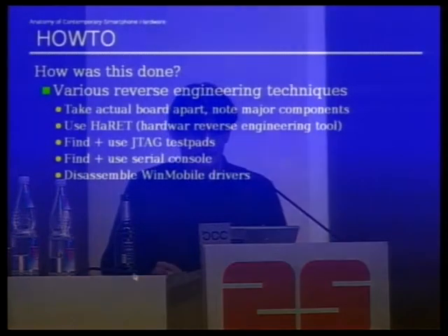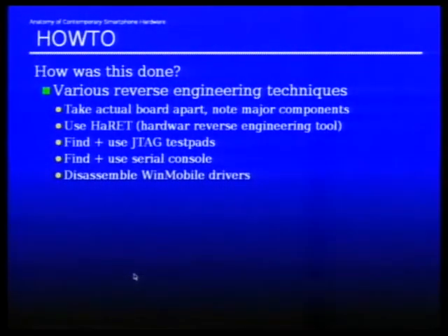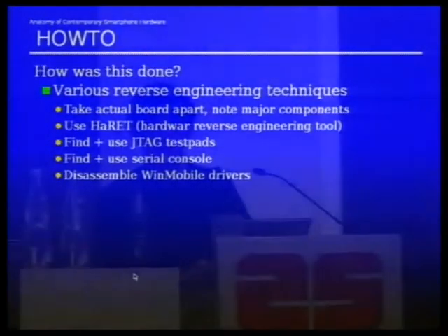So I started this project, the status of the project you can check somewhere else. So the question is, how does one go about understanding more of the various hardware in those systems? Well, basically you have a number of different approaches. Number one is take the actual board apart, take notes of the major components, Google for the identifiers on top of the components, try to get the data sheets, try to put together how the device works. This is actually fun, and I think I've been doing this with every device that I bought in maybe the last 10 years or so.